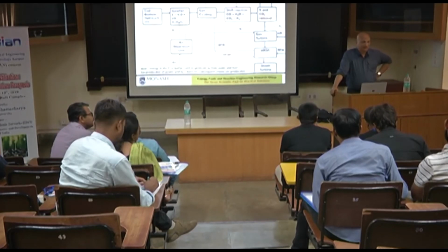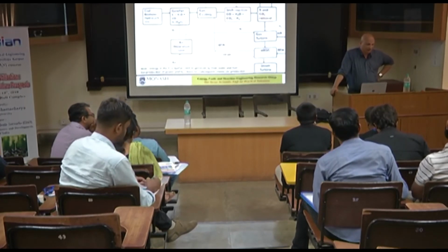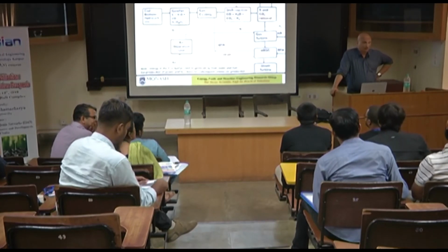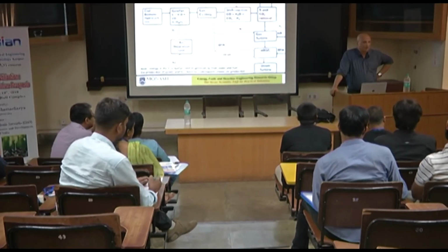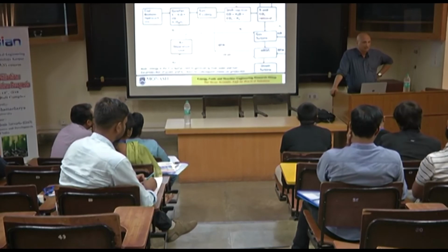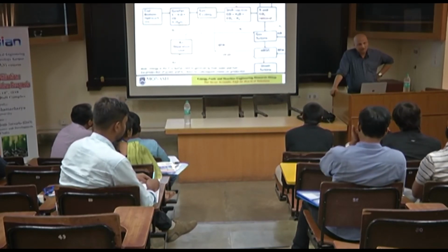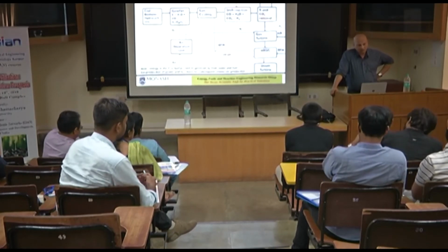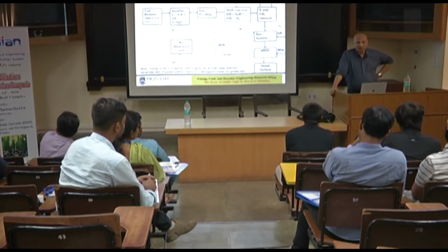You are starving the carbon of oxygen, so that it cannot go all the way to carbon dioxide, it can stop only at carbon monoxide. Not 100% to carbon dioxide, it will still have to generate some carbon dioxide, because that is an exothermic reaction, and the heat generated from the exothermic reaction is absolutely necessary to sustain the reactions that produce carbon monoxide and hydrogen, which are all endothermic.